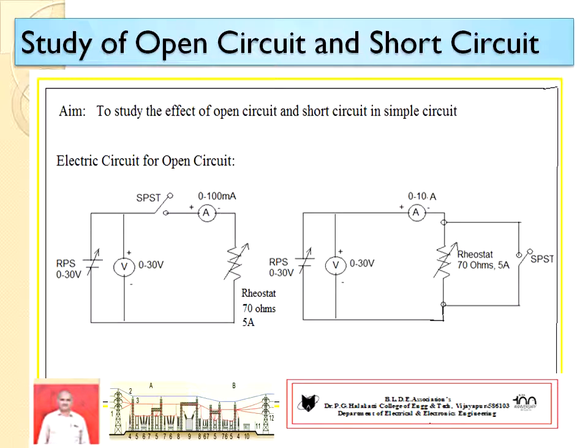So when the SPST switch is closed, it is called the normal working circuit. The circuit is working because it creates a closed electric circuit. Current will flow from higher potential to lower potential. Then the ammeter shows some amperes, it may be 35 milliamperes or some amperes depending upon the load rheostat value. So the load rheostat should be kept in cut-in position. When the SPST switch is closed, you take one reading, that is called the normal working current.